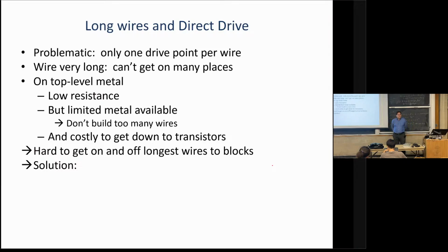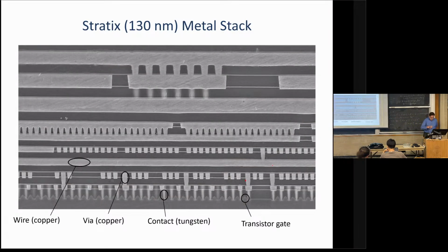Actually, a quick question on the last figure. Sure. Your switch block can go from a length 4 to like a length 8 or 16. Yeah. So if I wanted to do that switch, would I have to go down the metal stack to the switch block, which is in a transistor, then all the way back up to the highest level? Yeah, you do. Because in an FPGA, the switches are transistors. Which means, like in an ASIC, you could say, well, I'm going to use some of this metal layer, then I'm going to use some of this metal layer. I'm just connecting them with vias.